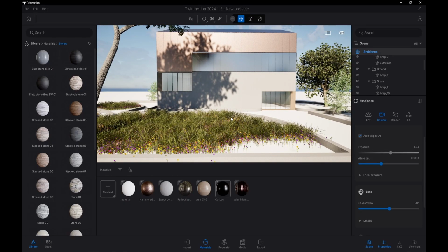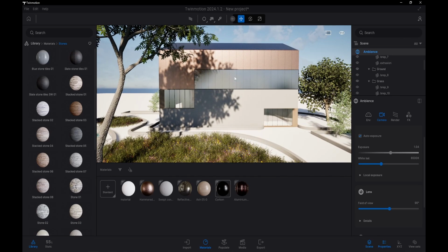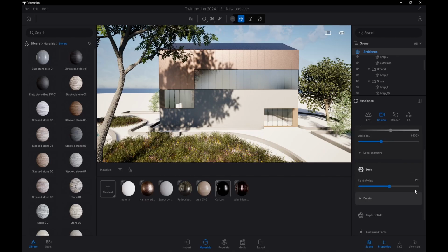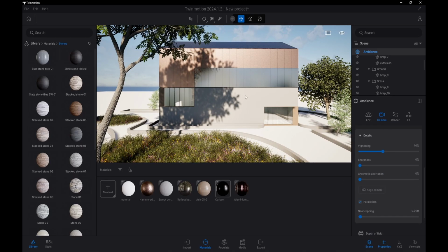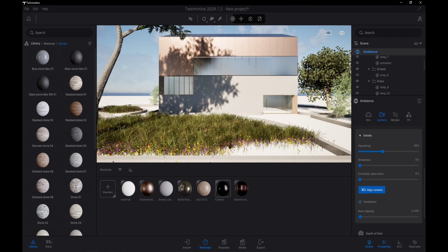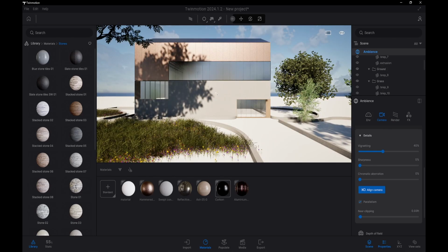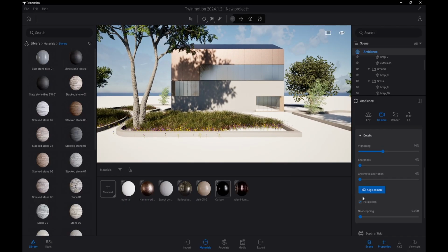And also, what I like to do when it comes to elevation shots, and this is going to matter a lot if you want this kind of textured collage-like rendering style, those views look best on elevation shots. You can also do perspective, but perspective elevation shots look the best in those types. So if I go down to my lens and go to details, I can do parallelism. You see how now it's flat, straight on, but also I can align my camera to whatever geometry. And now it's perfectly flat, aligned to this geometry. So now you're in perspective elevation when you do align camera.